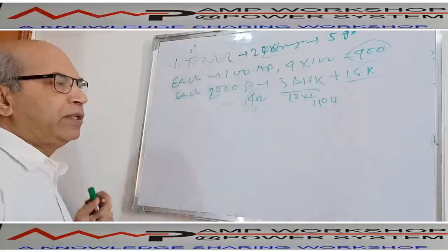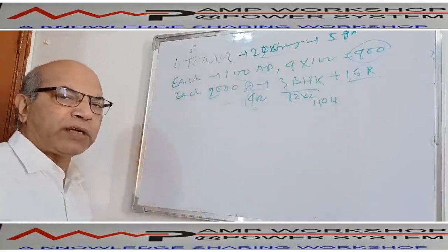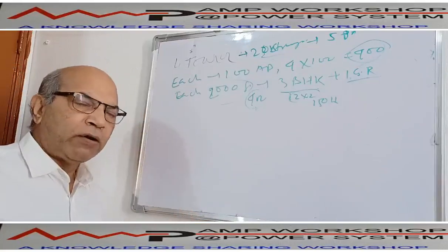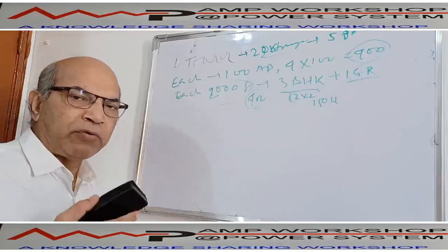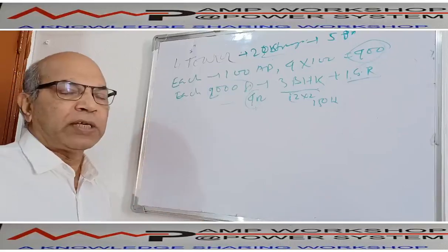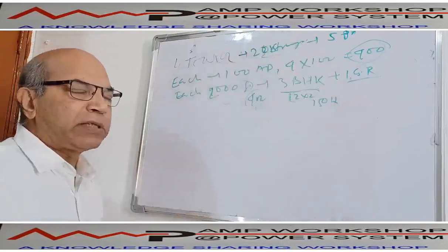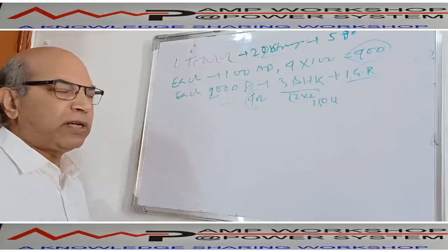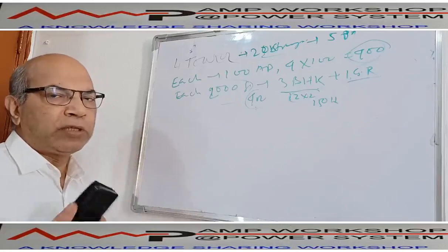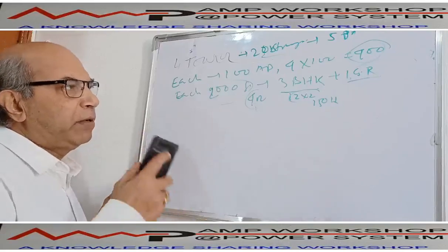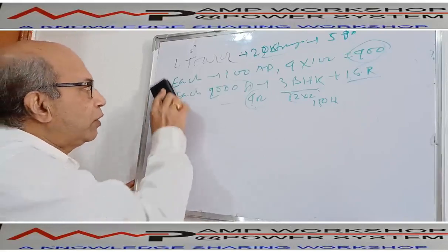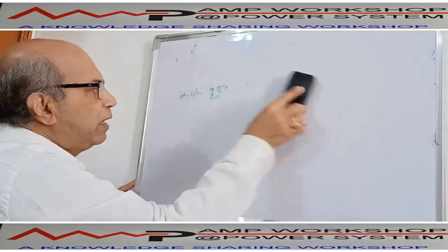If we want to electrify these apartments, we have to see what size of transformer either the company constructing this housing complex will provide, or the power supply company which has agreed to supply power to this complex needs to supply. Suppose the entire power will be supplied at 415 volt. What about the upstream transformer? That may be 11 kV or 33 kV or 22 kV, but the utilization voltage will be 415 volt 3-phase 4 wire. So if we want to supply these apartments without any interruption, what will be the size of the transformer? To start this transformer sizing, we have to start from each apartment.